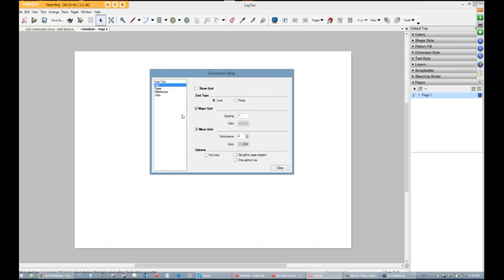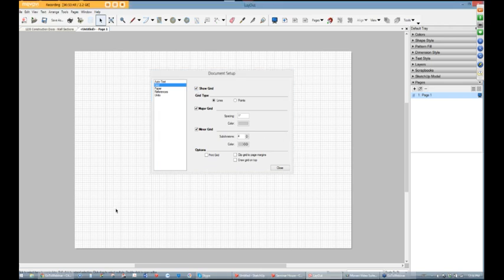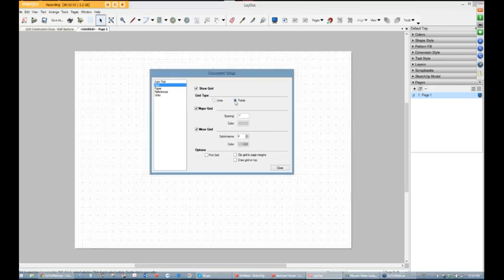Grid we'll get back to now. You can say Show Grid. So you have a grid showing. Now, that's not going to print, it's just reference. You can do lines or points. Not sure why anybody wants points. It's a little goofy looking. You can set up a major grid. This is real world numbers now, so 1 inch is actually an inch. And you can set up minor grids, which are subdivisions.